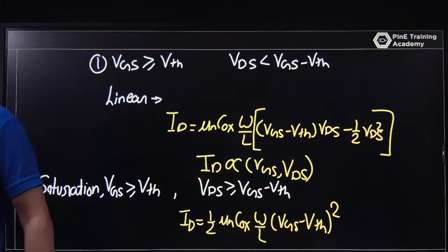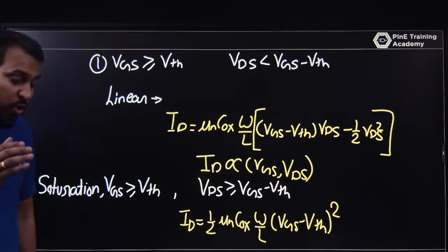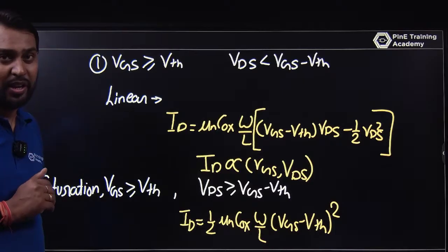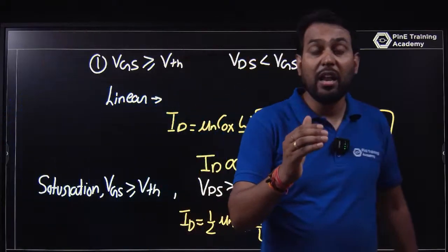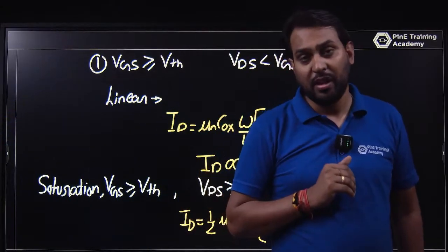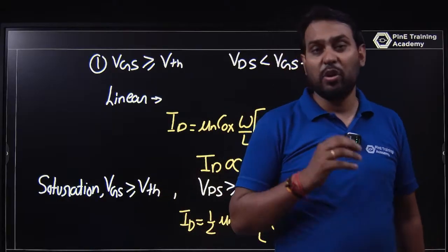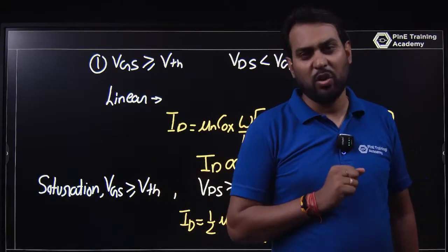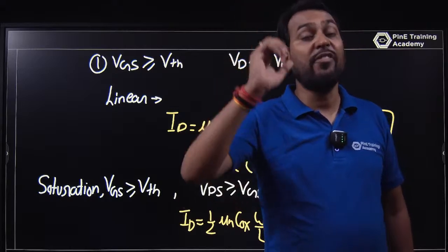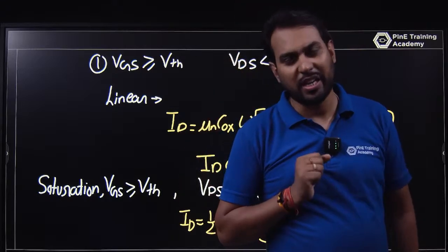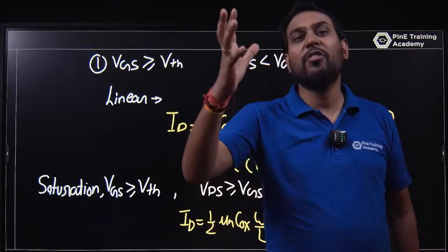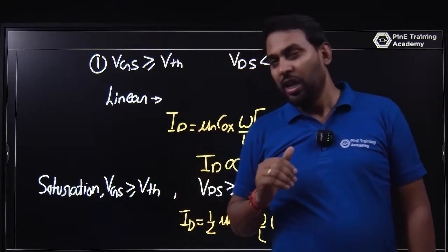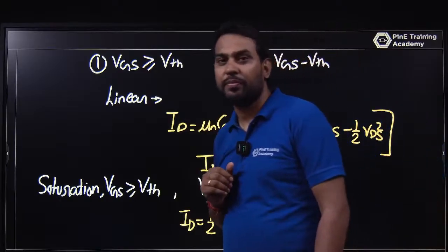These are a lot of effects introduced as per the lower technology. So as an analog circuit designer, we try to reduce the second order effects. How can you avoid them? You use a higher length. If you are working in 90 nanometer technology, you choose a length of 500 nanometer or 1 micrometer for analog circuit design. Why? As length increases, the second order effects will be less.